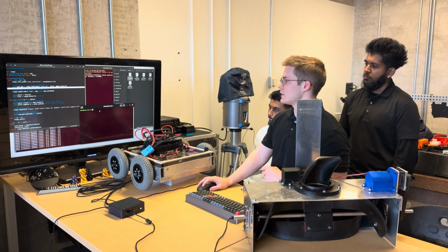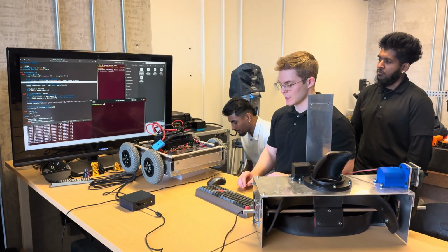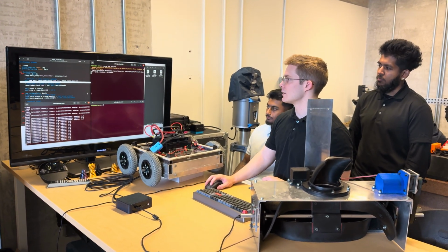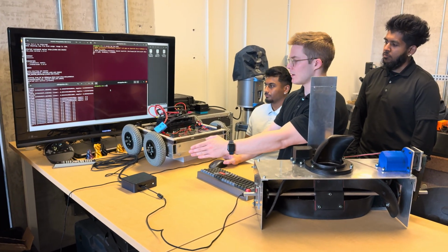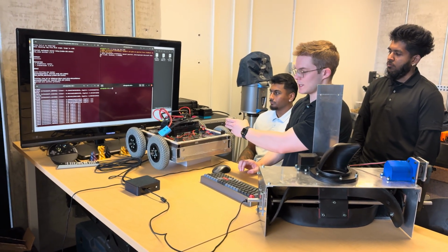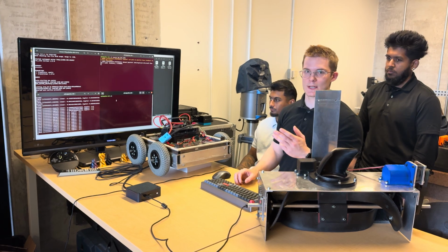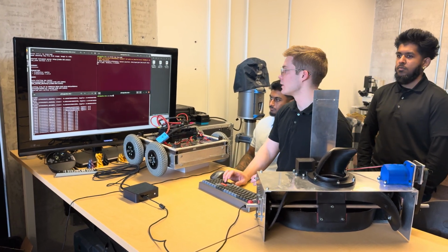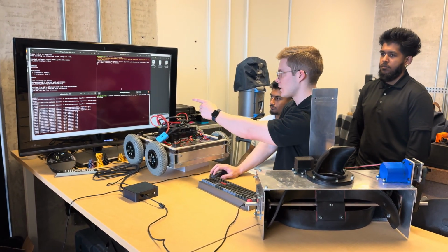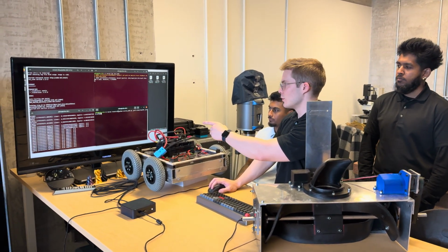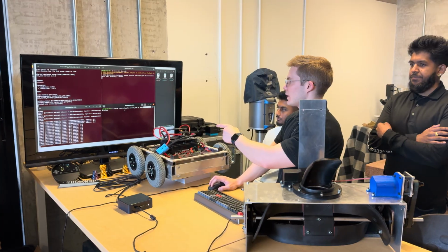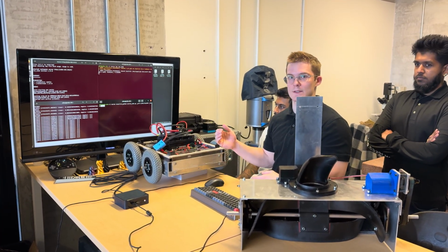The final thing we need to do to make sure that the robot runs is to create a serial connection between the mini PC here and our Arduino here. Because right now all we're doing is dissecting the information from the controller. So to create that serial connection, we need to run a serial Python node that is connecting at the specific port and the same baud rate as the Arduino.